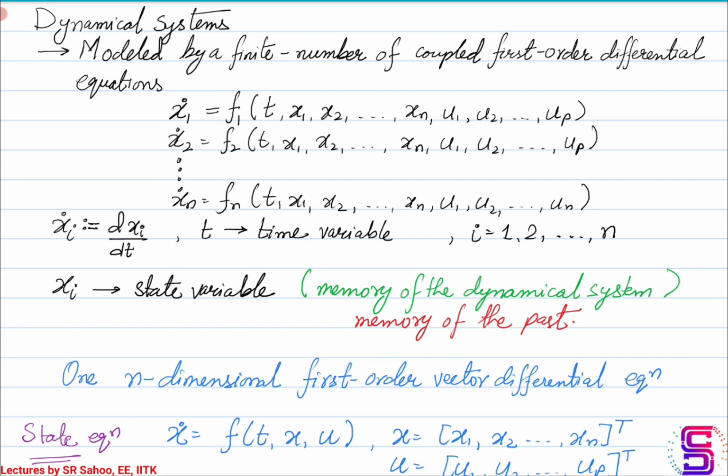For example, your spring mass damper system that you have always seen. But most of the systems that you would see around would possibly not satisfy the property of linearity, hence being classified as non-linear systems. Even for the spring mass system, even though it is linear, depending on the nature of the spring, the linearity property might hold only over small displacements. That is, the restoring force may be directly proportional to the displacement only over small displacements about the place of rest. However, over larger displacements, this restoring force may not be directly proportional to the displacement. It may have a non-linear dependence on the displacement itself.